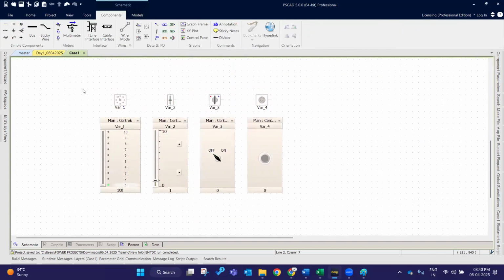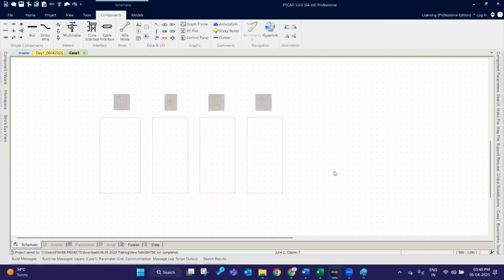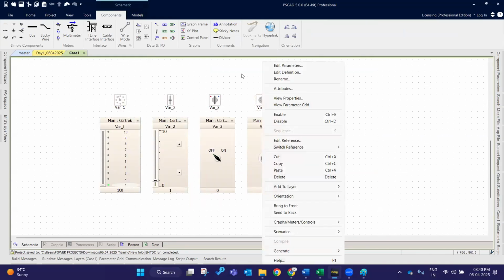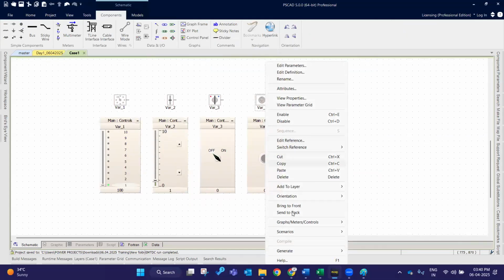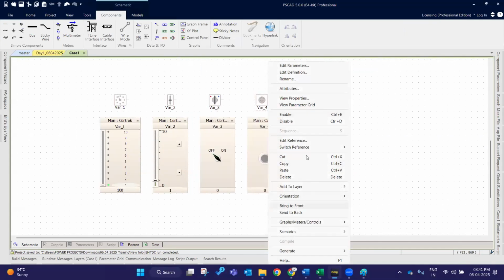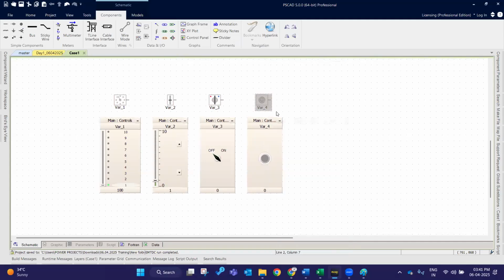So this components will be used, right? For disabling and enabling, just select all those, control D for disable, control E for enable shortcuts. If you want to disable this element individually means just select on that element. The same control D means disable. Control E means enable. You can use the shortcuts also. Yes, is that clear?